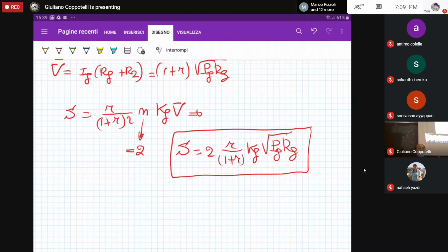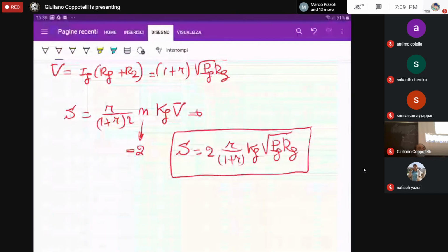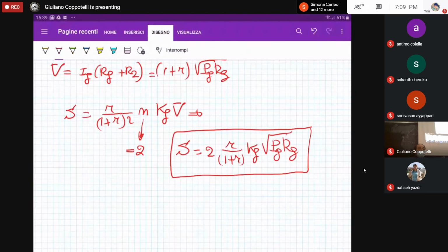If you need a number of measuring points, for each point you have to bond several strain gauges, and the electrical wiring and the complexity of the measuring setup start to become very important. So most of the time we are using quarter bridge or half bridge configuration.